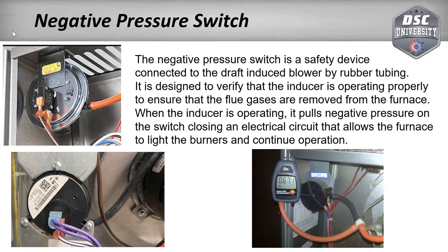We would test the negative pressure switch out here. I've got a digital manometer teed into the rubber hose so I can actually see what negative pressure is being pulled and determine whether I've got a problem with the inducer or a problem with the negative pressure switch itself.